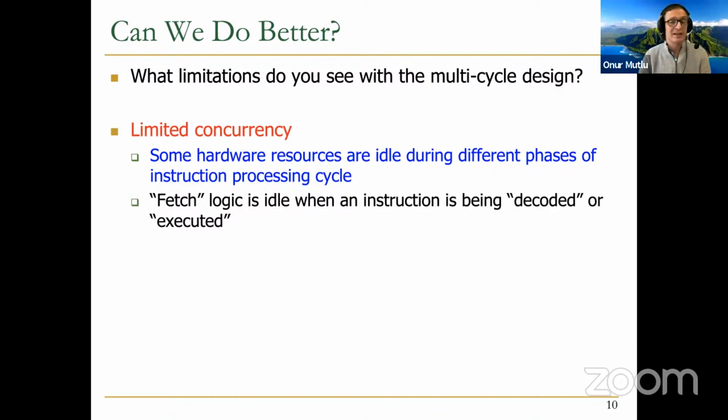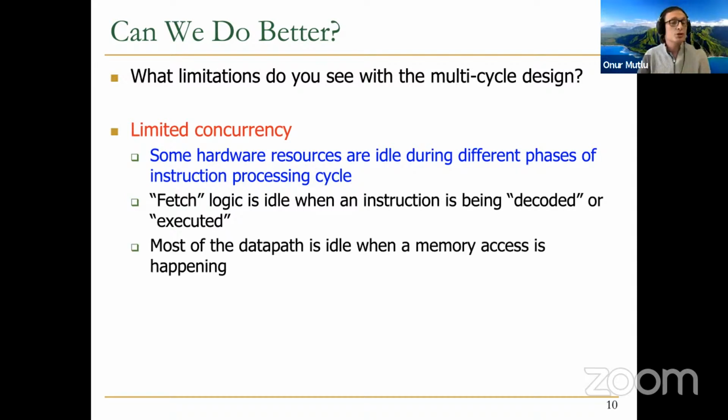Basically, fetch logic is idle when an instruction is being decoded or executed, or writing its result back to memory or register. And most of the data path is idle when a memory access is happening. ALU is idle, fetch logic is idle, write back logic is idle, register file is idle, decode logic is idle. You're just doing memory access for the instruction that happens to be in that stage. And clearly this leads to a lack, I shouldn't say loss of performance necessarily, but lack of potential performance improvement. We're not really utilizing the hardware in the best way to maximize performance.